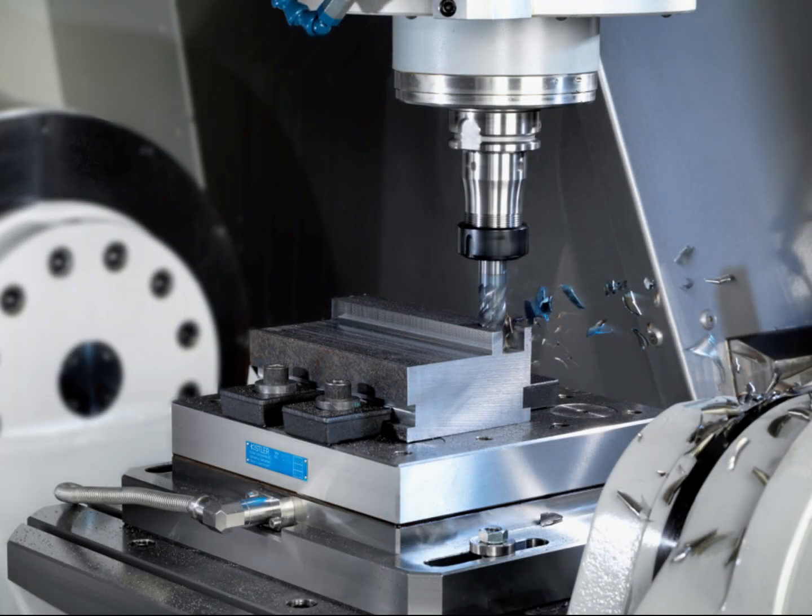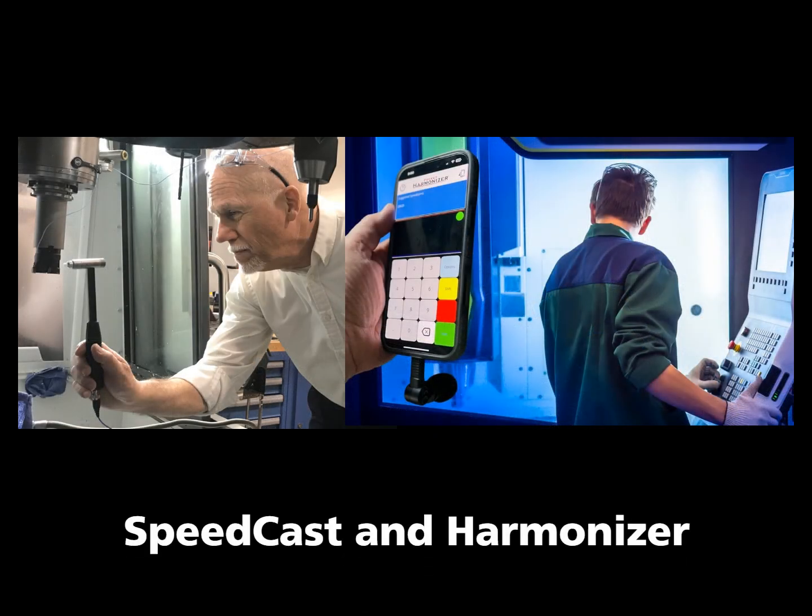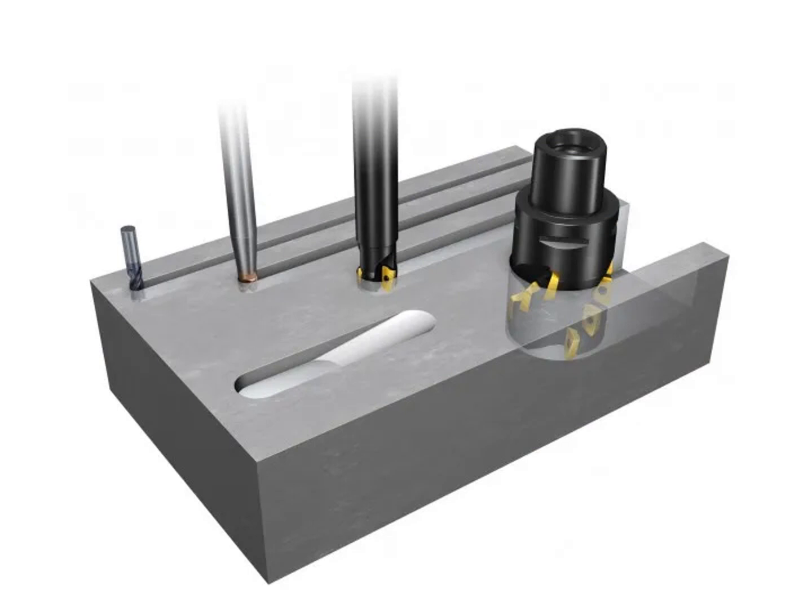Generally, cutting force and process damping coefficients are determined experimentally using the tool and workpiece material in question and measuring the force during cutting using a dynamometer. However, with Speedcast and Harmonizer you can replicate this high-level tool and material testing in the field. This testing method is for indexable milling cutters and slotting-capable end mills.